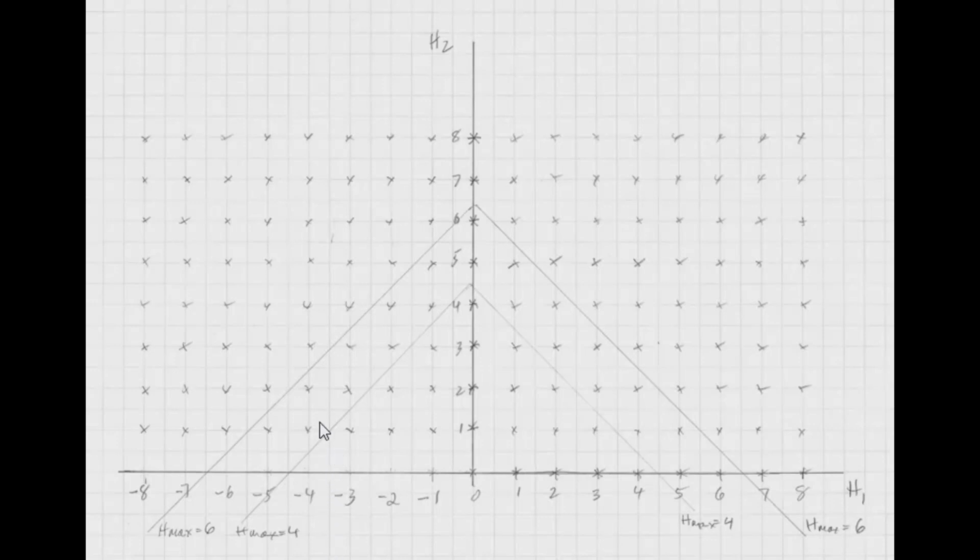Now, I hope I'm not getting ahead of myself a little bit, but when you have a two-tone problem, you have to be really, really careful about the excitation frequencies and the harmonic numbers, because the higher harmonics in the Fourier transforms, when you have more than one tone, are often not very good. They're actually garbage a lot of the time.